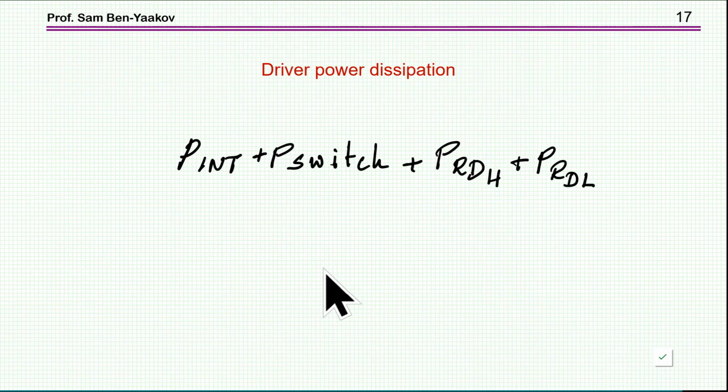So as it stands now, we can calculate the resistive part very easily. And also we can get an estimate of the quiescent current for the unit. But this part here, the actual switching loss of the driver due to the current passing through it, which could be a high current, this information is not very well documented. So there is a question here.